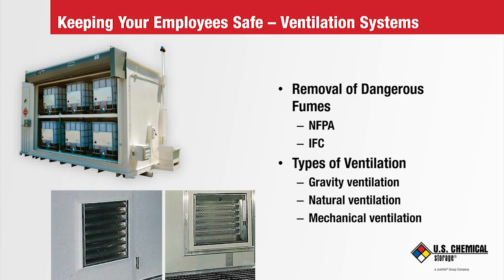The International Fire Code, paragraph 2704.3, says the fan is to run continuously, have a break glass shut-off switch, and an exhaust vent located within 12 inches of the elevated floor. The exhaust air shall not be recirculated back into the room. In addition, it is important to know how the exhausted fumes mix with the outside air. NFPA also says the fume discharge shall terminate above the roof.